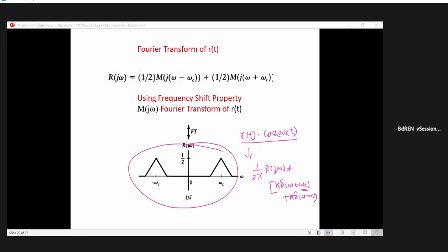at zero and ωc. At this point, the 0 will be shifted here, isn't it? That means the whole figure, for example, will be shifted in either direction. Okay, try to figure out how your figure will look. You will see that another spectrum will appear here as a result of the shift. Then what can you do? Then you apply a low pass filter there to extract this portion out.